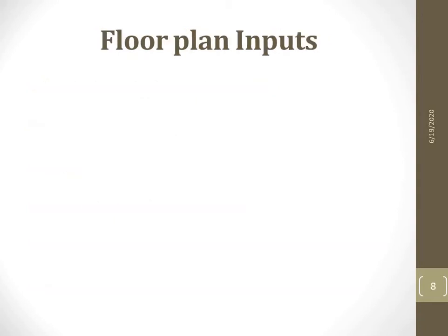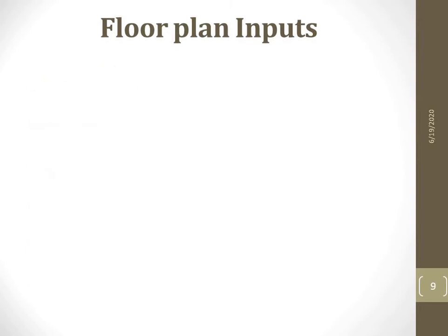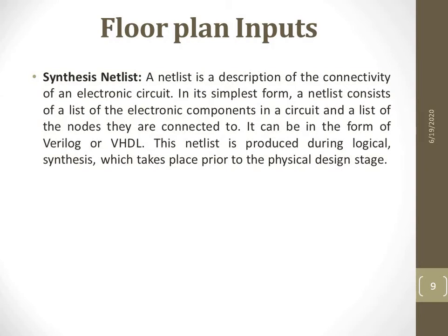Next, what are the floor plan inputs? Floor plan inputs are a synthesis netlist. They can be from physical libraries, from logic libraries, from timing constraints, from power requirements, and floor planning control parameters. So let's see in detail each and every one. First we'll see the synthesis netlist.